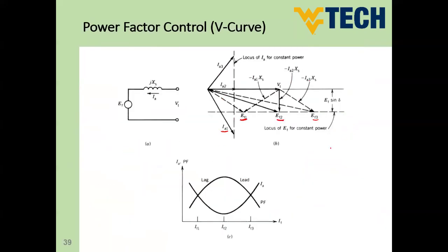So this means, guys, we can conclude from this phasor diagram that if we control the excitation value, and we can, because excitation is a DC source, we can control the excitation using the DC source that supplies the field winding, and this is accessible. We can control that using a variable DC supply, for instance.